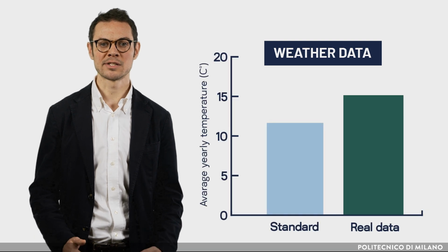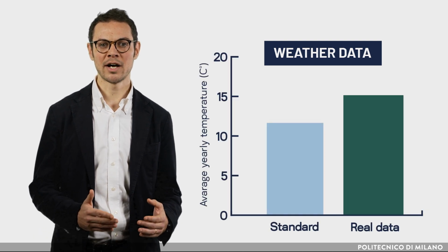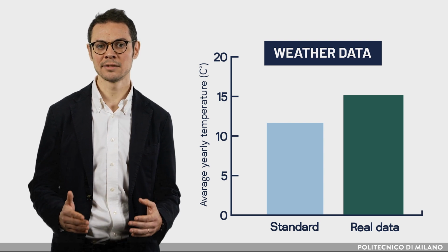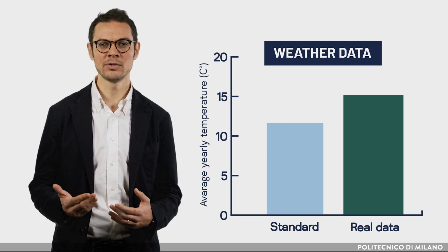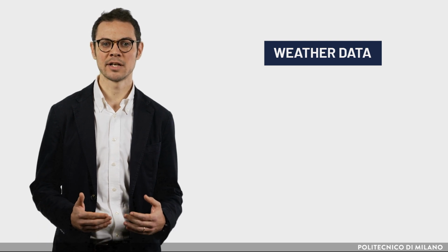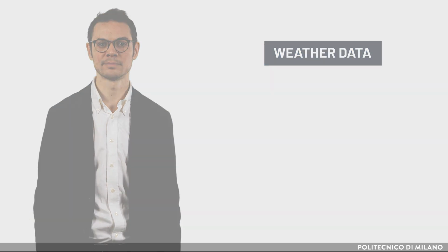Finally, the hourly weather data related to the building site must be selected. In such respect, several databases provide a historical set of data gathered in a file easy to upload in the simulation tool. However, in order to carry out a detailed assessment, the historical data cannot be considered reliable any longer due to climate change. In such respect, a tailored weather file can be set up based on the updated measurements provided by the closest weather station.